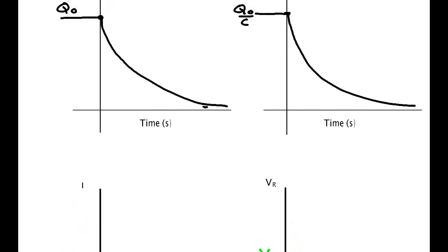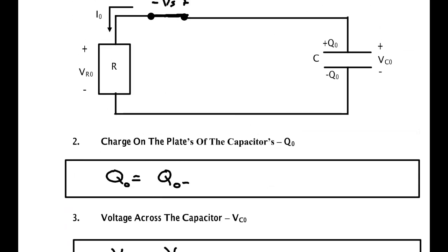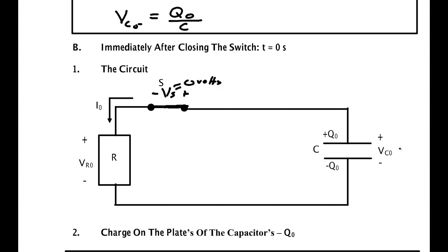If you work with televisions or any other type of electrical thing and you have large capacitors, you need to be careful. These capacitors look like cans, and if they have a physical size comparable to your hand, they may have enough energy to vaporize a screwdriver and kill you. There is a circuit that when you unplug the TV is supposed to constantly bleed off this charge over some time so as to protect you.